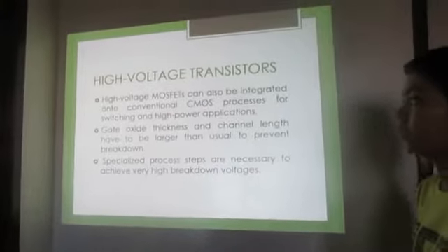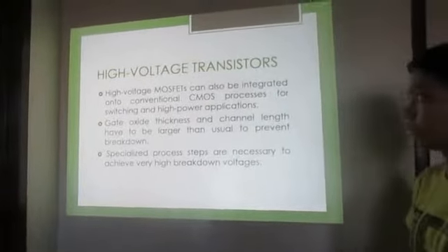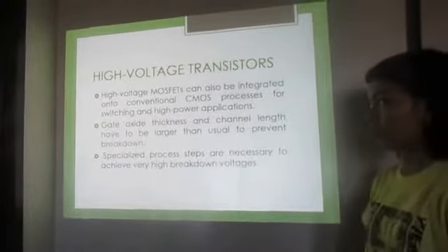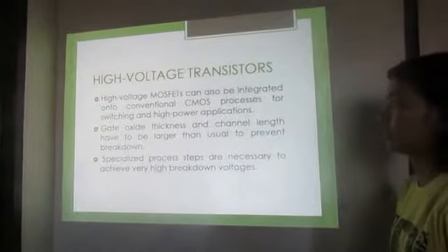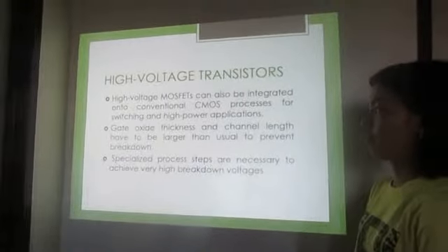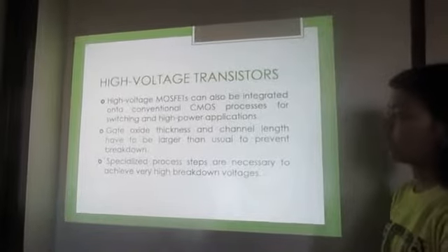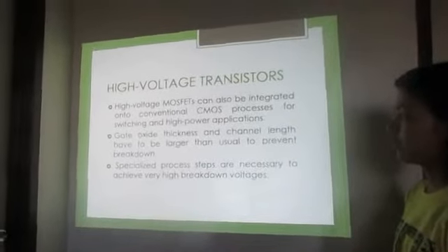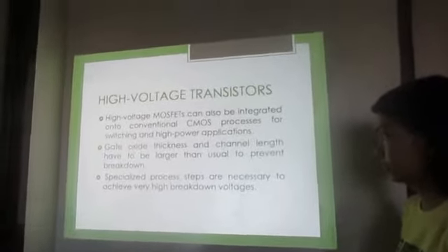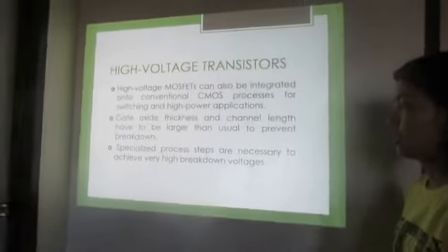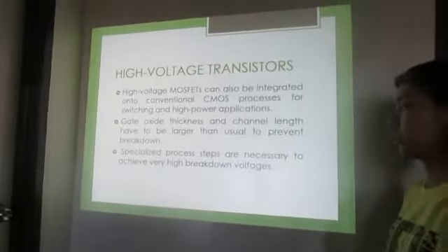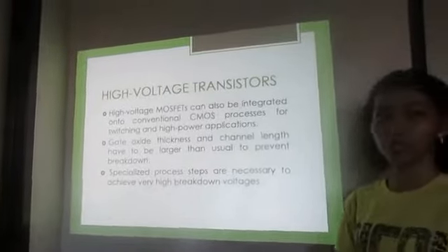High voltage transistors. High voltage MOSFETs can also be integrated onto conventional CMOS processes for switching and high power applications. Gate oxide thickness and channel length have to be larger than usual to prevent breakdown. Specialized process steps are necessary to achieve very high breakdown voltage.